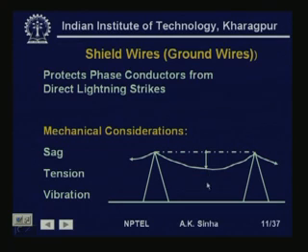It also has to be there if people or any vehicle is moving, which also will get stressed by this electrical field, and therefore, a certain minimum clearance is required. This is given by certain standards, like for a 400 kV line you need around 12 meters of ground clearance. That is, the minimum ground clearance should be around 12 meters.